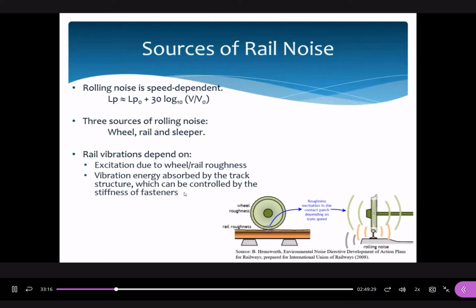The working principle of this floating slab is like this. We install a concrete mass, and then below this one, please remember, not only do we put in a concrete mass, we also need to install isolation systems below it. Otherwise, it is similar to a rigid structure, and the force can still directly go through the structure to the surrounding environments.